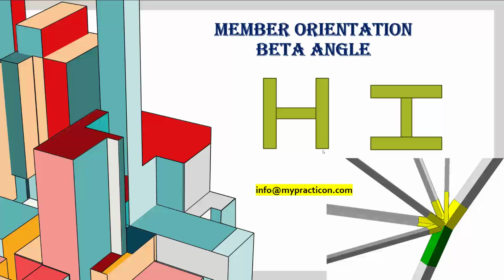Basically, this member orientation is also associated with strong and weak axis bending. So we should not ignore it when working with sections like I sections, channel sections, T sections, or unequal angle sections.